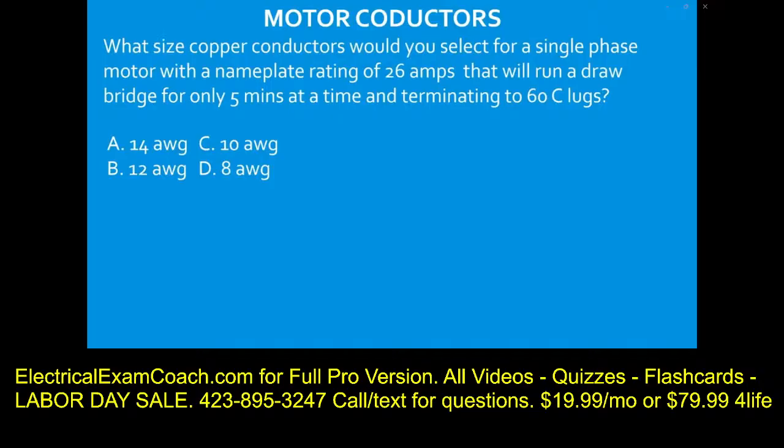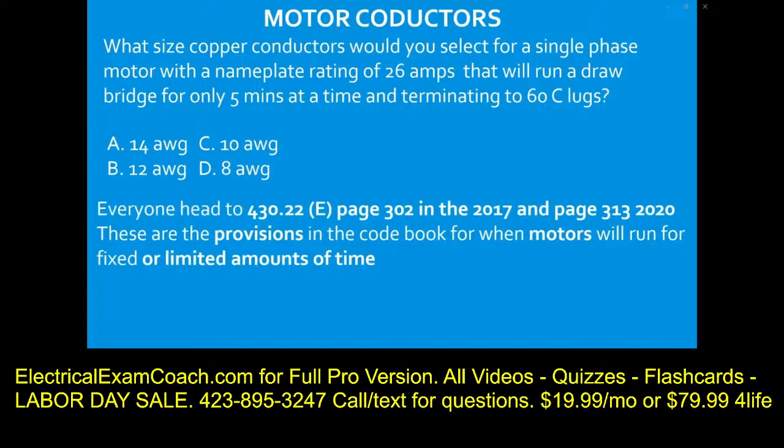So, this is not a normal situation, is it? That's what you learn to watch out for when sizing motor conductors. Is there anything different going on? And in this case, there is, so we're going to slow down and figure it out. Everyone head to 430.22(E). It's on page 302 of the 2017 and on page 313 of the 2020.